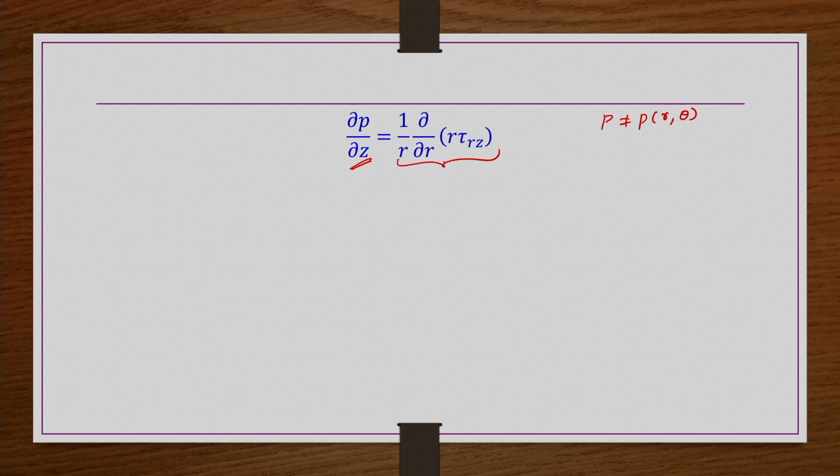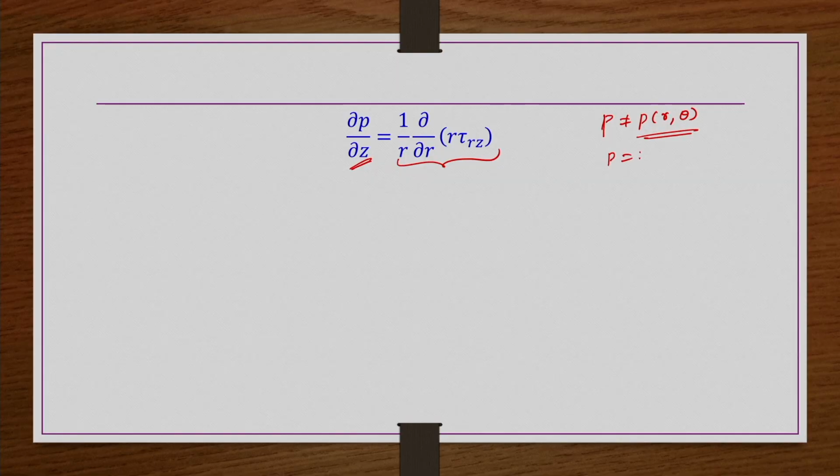So, then for the left hand side term, the right hand side term is nothing but a constant, because the left hand side term, the pressure term, we already realized is independent of r. So, that is the point of simplifying all equations of motion. So, you get certain information definitely which is going to be useful, right. So, now we understand it is only a function of z from this z component of momentum equation. So, the right hand side term is all a function of r. So, then for the left hand side term, the right hand side term is a constant.